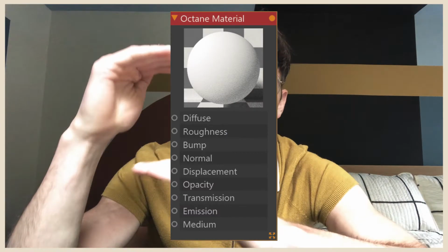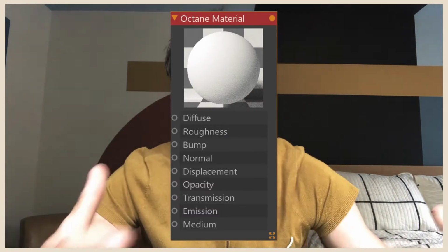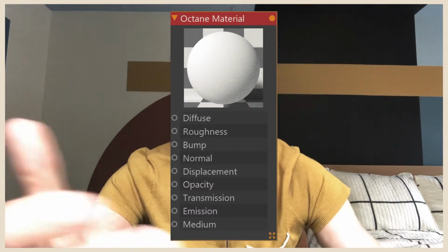If I wanted to put this image of my dog onto this object, a coffee cup, I could do that, easy peasy. Okay, that's a material in its simplest form. But what if we want there to be texture, depth, shine? That is where channels come in. There are channels for everything: color, roughness, bump, opacity, reflection, and many, many more. One material has all of these channels built inside of it, and you can choose which ones you need to make your material come to life.